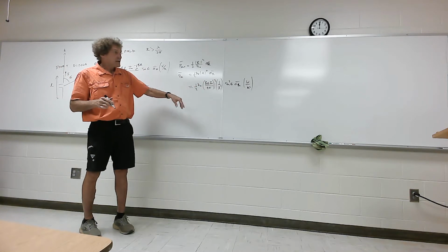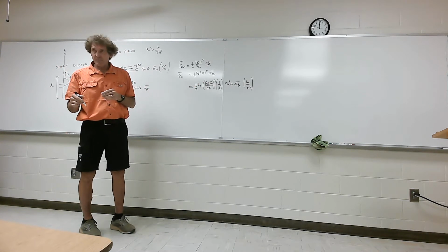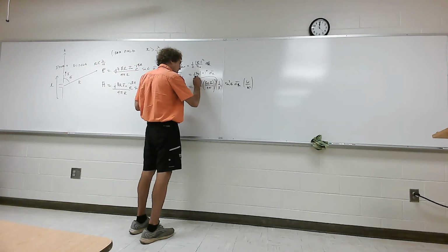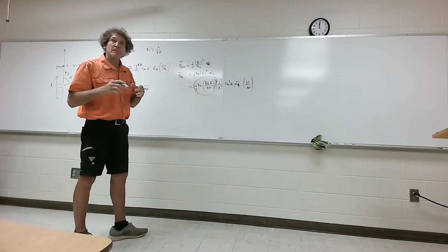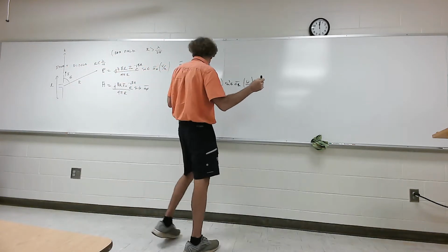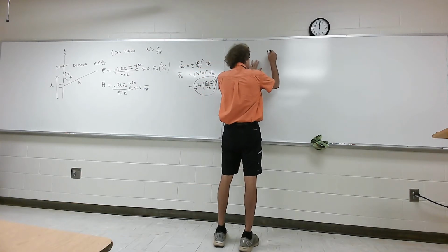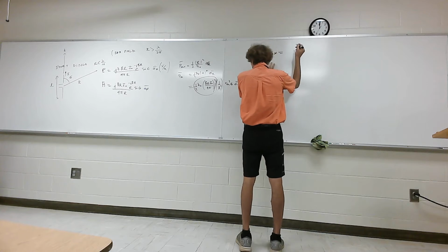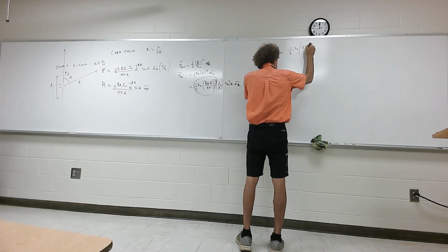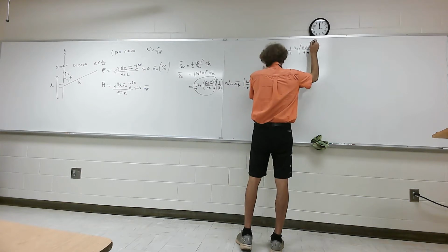That will work. Now, what most of the time is smart to do is take all these constants right here and just call that some P max. Y'all follow me? So create a new constant, and I do that all the time. Called P max, and that's equal to 1 over 2 times eta naught, times beta L I naught over 4 pi, squared.